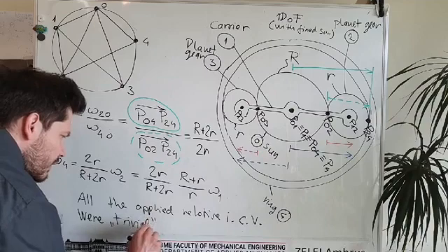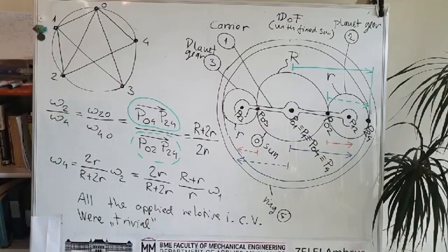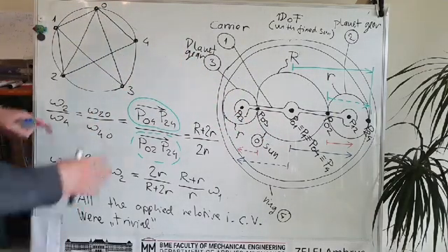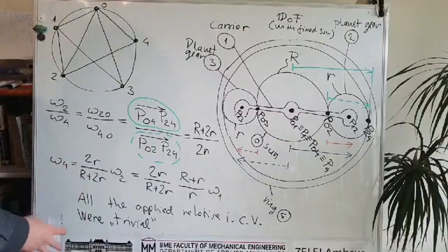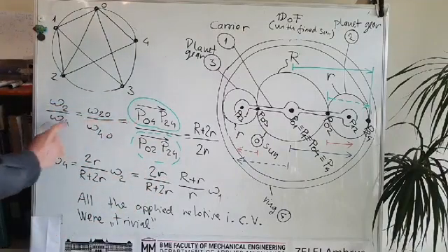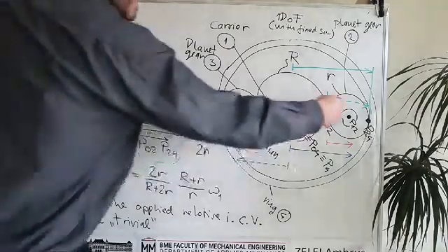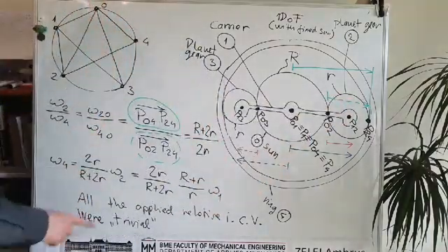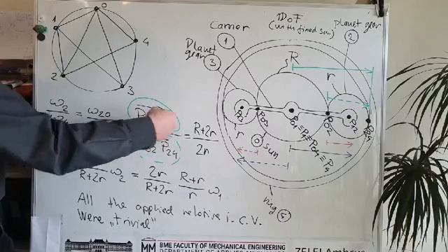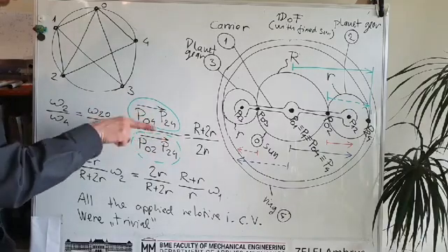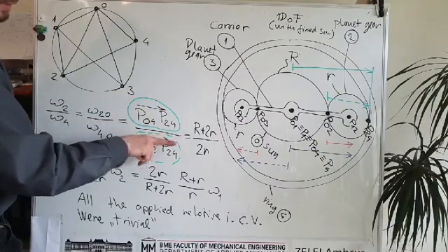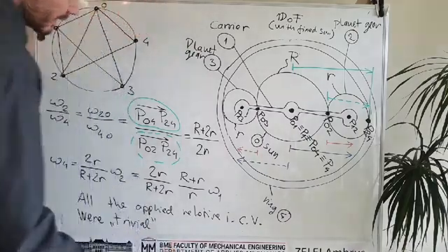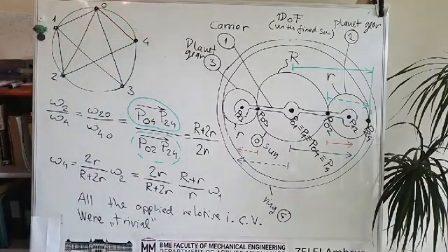So we didn't use the Aronhold-Kennedy theorem, but we used this algorithmic way to compute these points, and we also used this formula for the ratio of angular velocities, which is only related to the distances. The important message is that the distance is directed, so it does matter if it points in the right or the left direction, so we always have to keep it in mind.